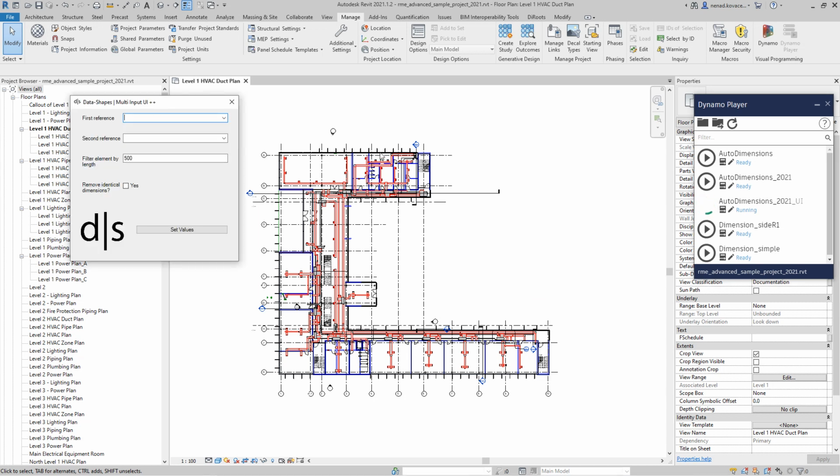And also from this video and in the future, I will use Autodesk Revit 2021 regarding Dynamo. That is probably version 2.6 point something, we will see. So now we have a user interface in this script. We can choose either cable tray, duct, pipe. With small modification, this script also can work for other elements, but I chose to test the script on those categories. So in this case, because I have ducts here, I will choose ducts.